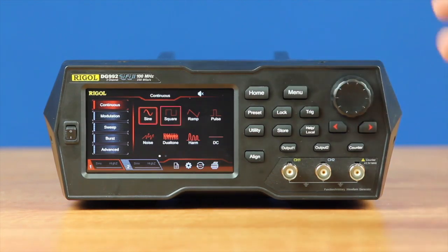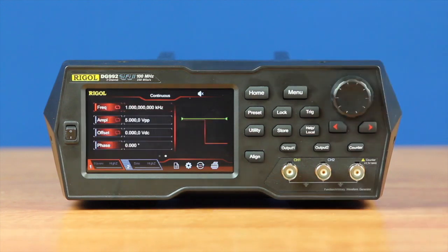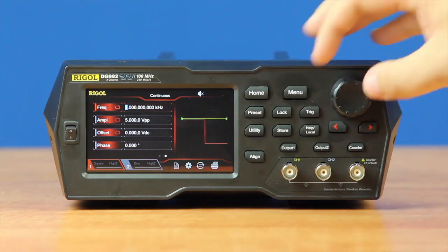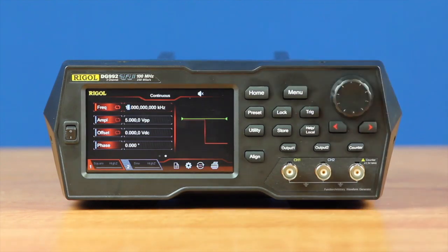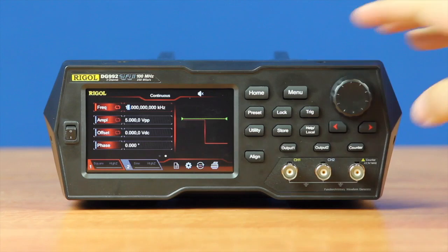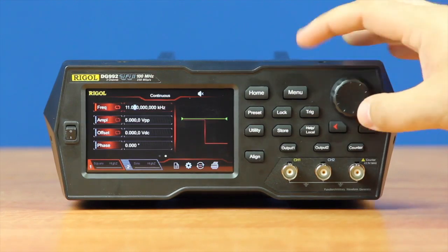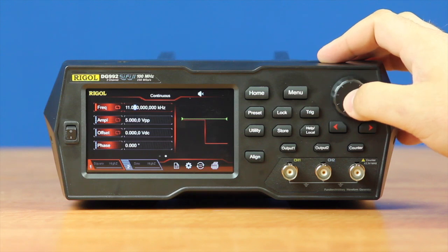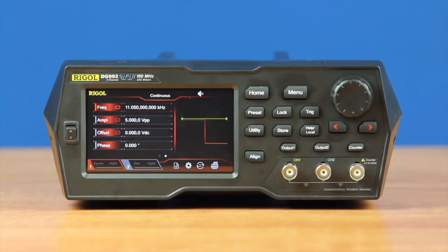So we can select a square wave with that, and we can press on it, and this will bring us to our home menu for this section, which now we can change our amplitude, frequency, and so on. And to do that, we press on our highlighted section, and then we can increase the frequency by using the potentiometer, or we can use the arrow buttons to move around to change different points if needed. And then once we've fixed a value that we're happy with, we can press on it to enter it into